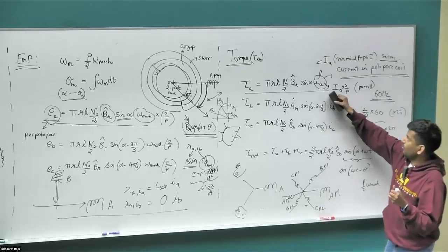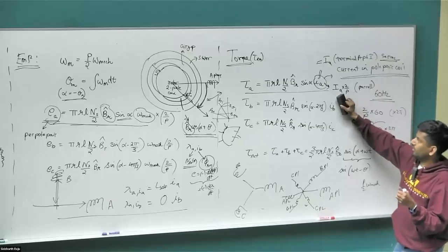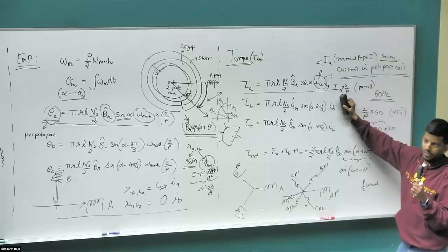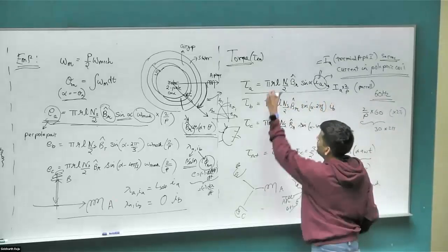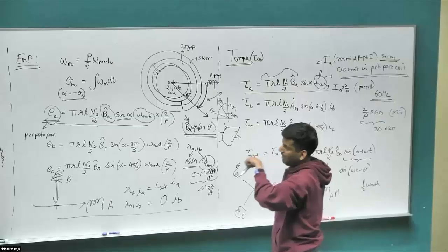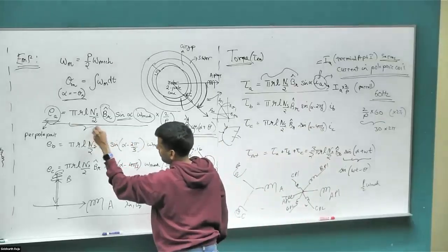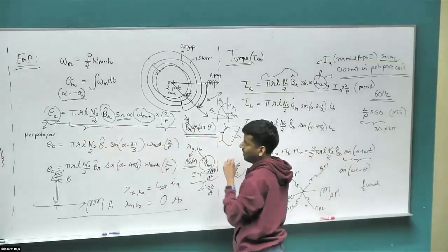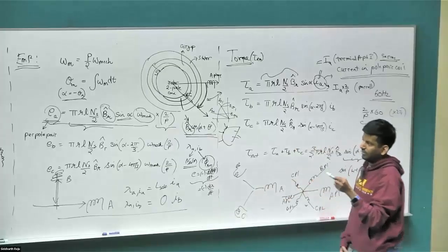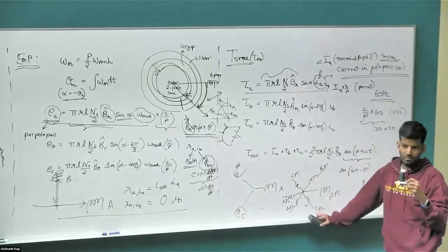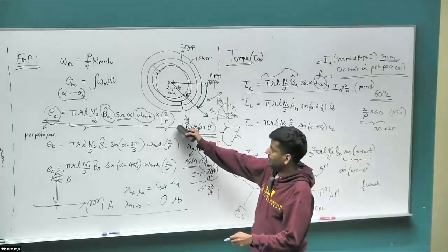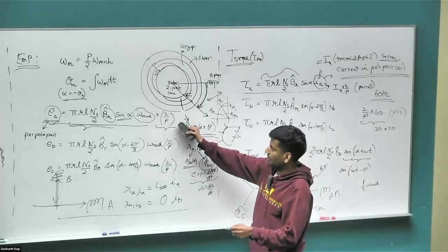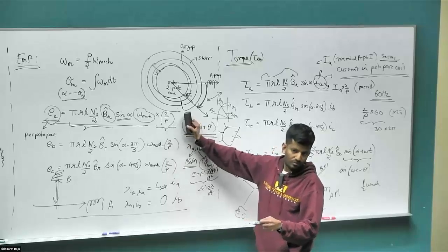So each of these coils would carry a current of just 2 by P times whatever the terminal current coming into the motor is. If we go back, these two expressions, the tau A coefficient and the E coefficient, initially look a little bit different because of this 2 by P term. But they do end up cancelling out in such a way that the Ke, Kt constants would still be the same for both the motors. Because if I connect them up in series, you would multiply by P by 2 and this 2 by P and P by 2 would get cancelled.